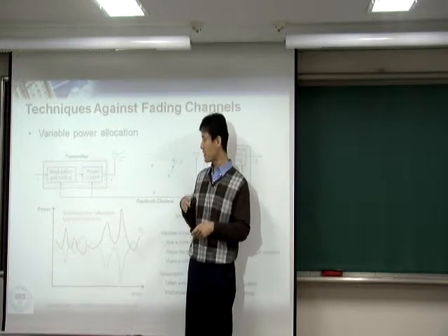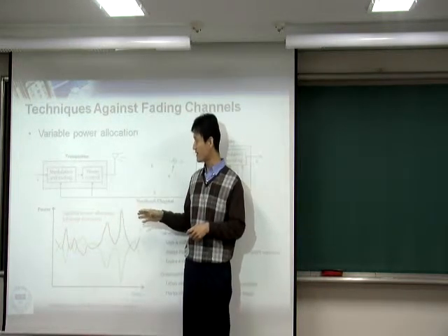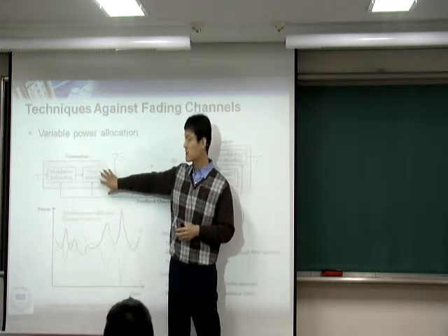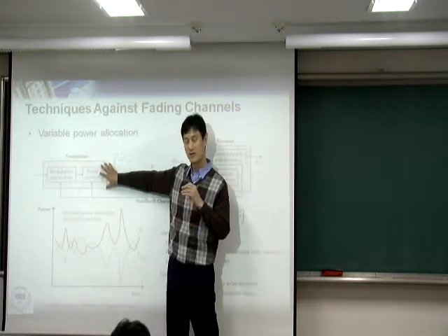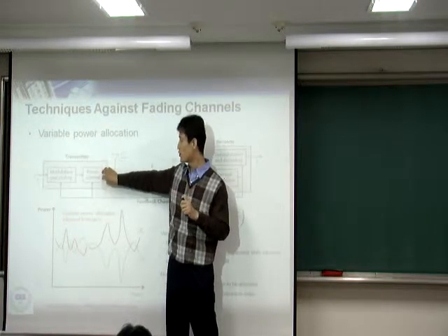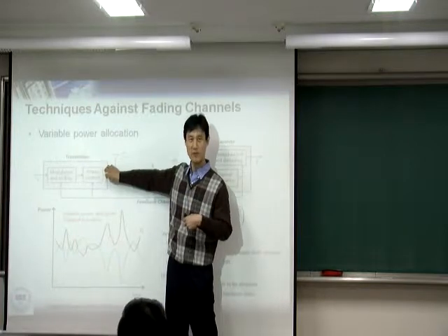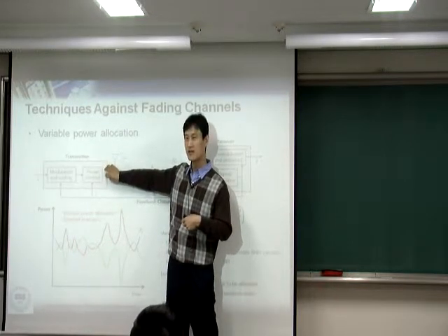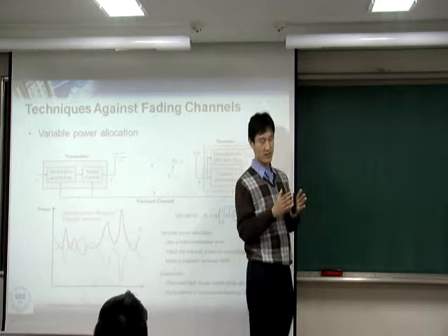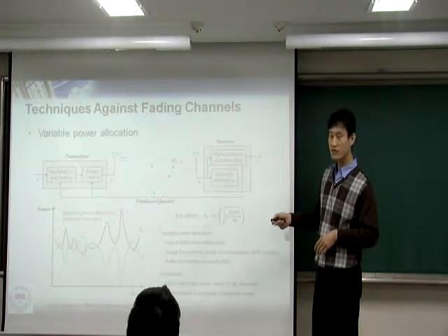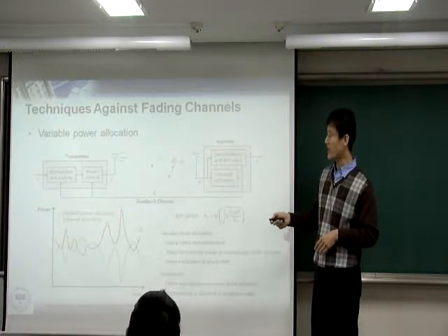But even if you had the power budget, that is not preferable, and not possible in an actual system, because in the transmitter you have a power amplifier in the circuit, and that power amplifier has a certain linear region, and so on, so you actually cannot do that. Your transmitter cannot be infinite.